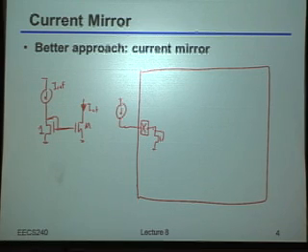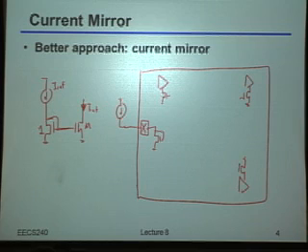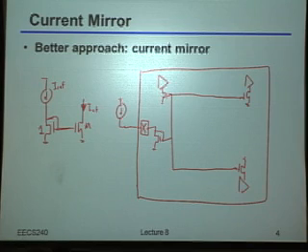So let's say indeed you did that. And now I'm going to ask, or we're going to ask you guys, the question: let's say I've got a bunch of amplifiers all over the chip. And actually, let me draw this the other way just to make the drawing easier. Right, and each of these amplifiers needs some bias current associated with it. And again, I want to slave all these to that known reference current that's external. So again, the simplest thing I might think to do is just take that reference current, feed it into that diode-connected transistor, and then just feed that gate voltage out to each of these transistors here. Okay?